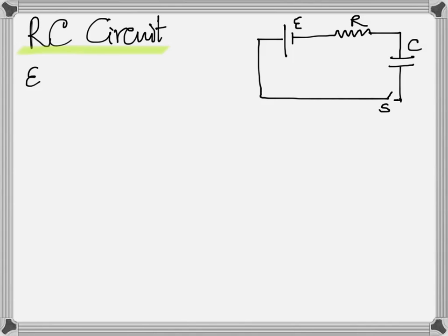Okay, if you look at the circuit, at any instant, let's say that there is a current flowing through the resistance, which is I, and I is changing. And so is the charge on the capacitor changing. We're looking at the charging process. When T is 0, what's the charge on the capacitor? When you just switch on, what's the charge on the capacitor? It's 0. And as T progresses, the charge on the capacitor builds up, and so does the current flowing through the resistance.